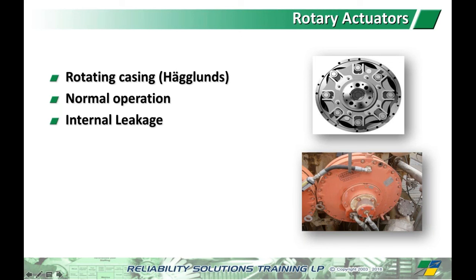One of the key elements of this unit is it has to leak to lubricate itself. So these pistons are designed for a little fluid to go past the pistons, and that's actually what's lubricating the rest of this thing. That is taken away by this pipe right here, which is a case drain. By the way, I'm not happy about that flow meter on that case drain.